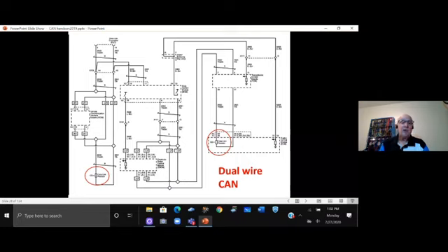And by the way, it can also be in the fuse box. There are a couple of Buicks on the road and a couple other cars too, but Buicks primarily, that have in one of the fuse boxes a 120 ohm resistor. So when the student comes up to you and says, hey, Al, I need a 120 amp fuse, you know he's in the wrong spot, okay? And obviously, if you put a fuse in there, the fuse isn't going to blow, but what you've done is you've connected the two sides and you have had an impact on data communication.